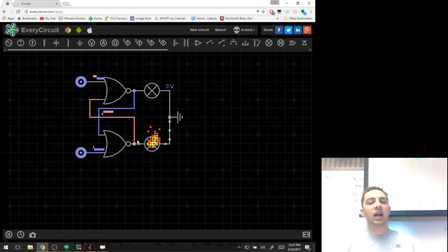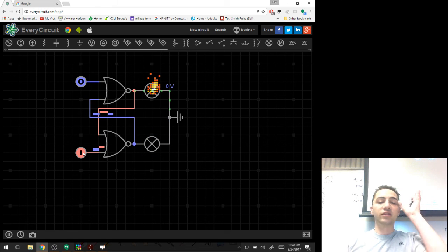Because I have some knowledge already, in state 0, 0, where they're both 0, it looks like right now I can twiddle this bit and it doesn't affect the output. It still always leaves this guy on, okay? And that's okay, because you're going to see that this 0, 0 state is actually a hold state. It's going to just not affect things. Let's do something that makes it change.